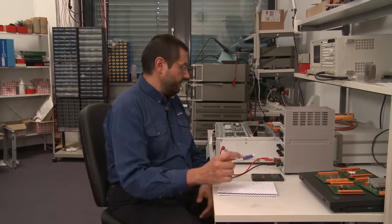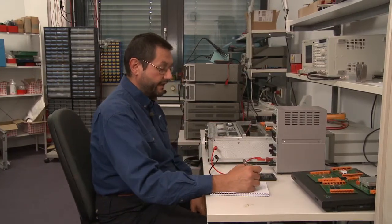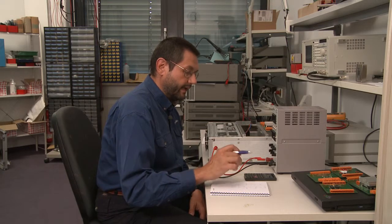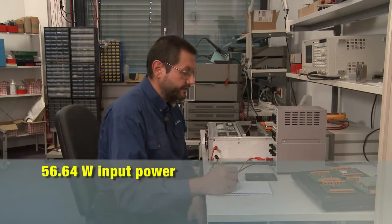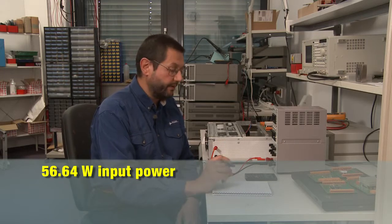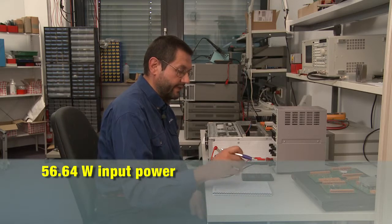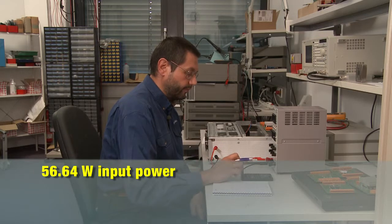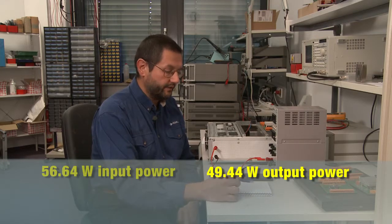Now that we have collected all the experimental data, we can complete our calculations and verify the thermal characteristics of our system. The input power to the system can be calculated by multiplying the input voltage by the input current. So we have 24 volt input multiplied by 2.36 amps gives us 56.64 watt input power. The output power as well can be obtained by multiplying the output voltage by the output current. So we have 24 volt multiplied by 2.06 amps gives us 49.44 watt.